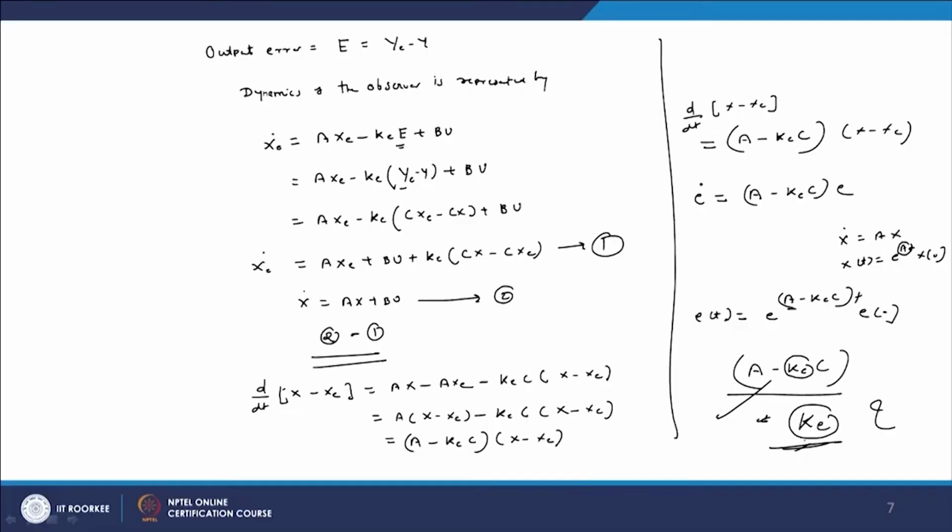That is why here we have taken the K matrix, the K from the error between y and y hat. When it comes to here, the K plays an important role. This is because eigenvalues depend upon the subtraction of A minus KC, and as the eigenvalues are far away from the imaginary axis, the error reduces to 0, and this depends upon this K matrix.